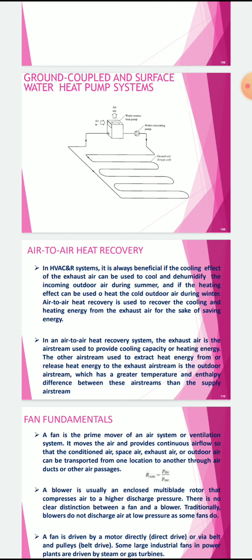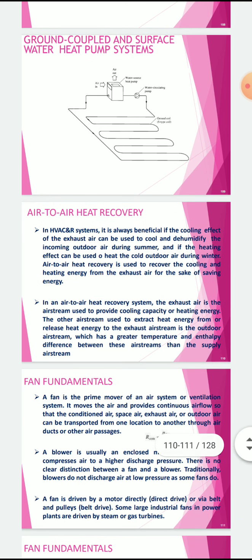Air to air heat recovery is used to recover the cooling and heating energy from the exhaust air for the sake of saving energy. In an air to air heat recovery system, the exhaust air is the airstream used to provide cooling capacity or heating energy to the other airstream.